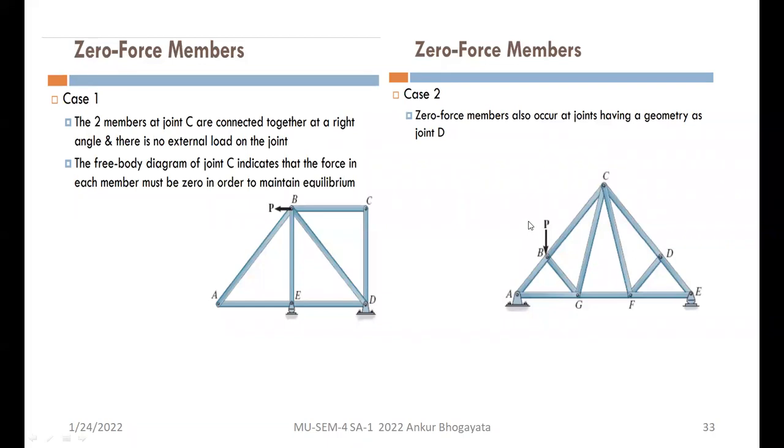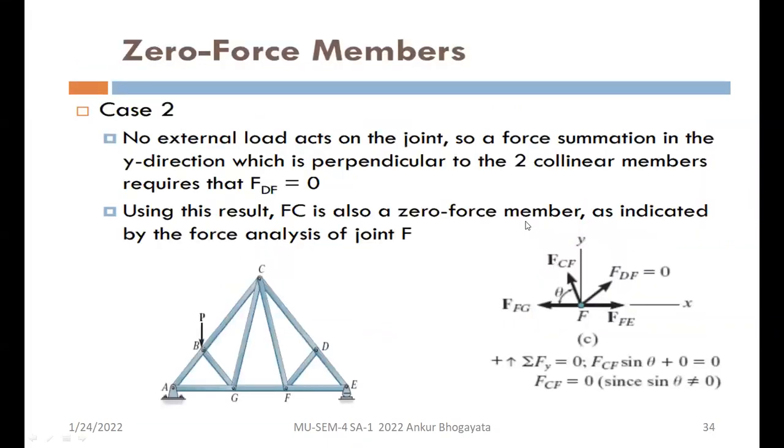In this process, you can definitely put the equations for any of the connected or selected joints, joint D, joint F. You don't need any information about distances or angles; directly you can determine the basic sense of the equations, and it will reflect which member forces should be zero, right?